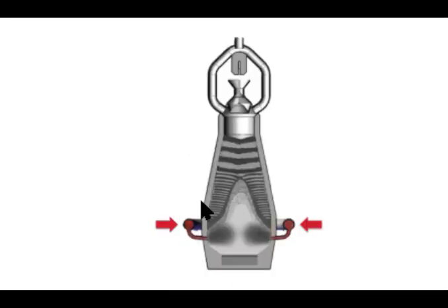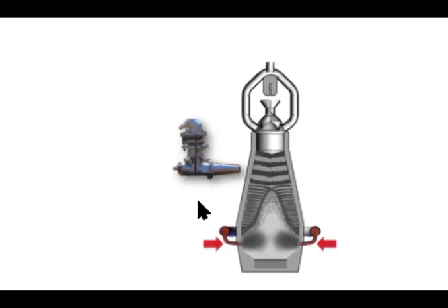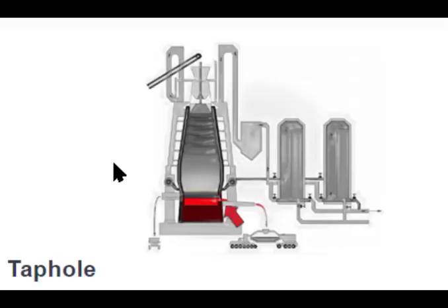So this is called the bustle pipe, where the task of this system is to provide the tuyeres with hot air. And what we see here is a tuyere. Depending on the size of the furnace, the wall of the hearth is radially fitted with some 20 to 40 water cooled copper nozzles called tuyeres, which are used to inject the hot blast into the furnace from the hot stoves through the hot blast main and bustle pipe.